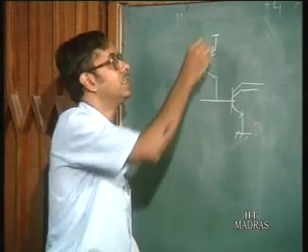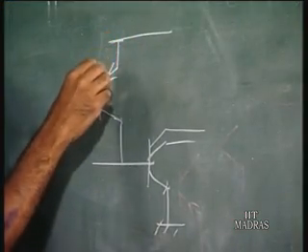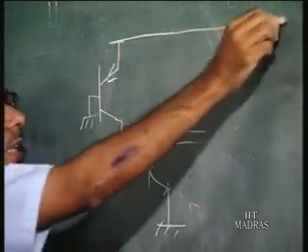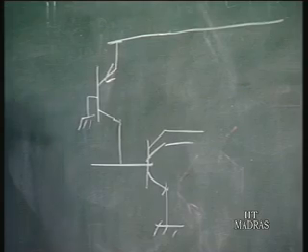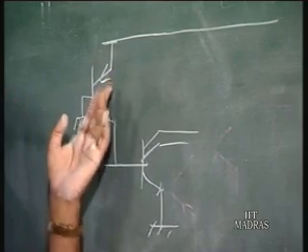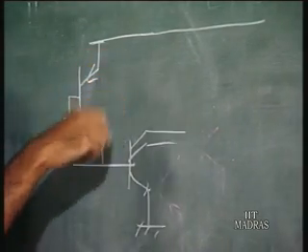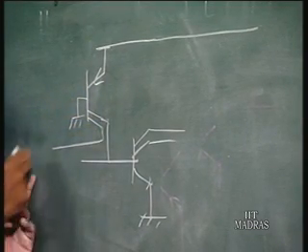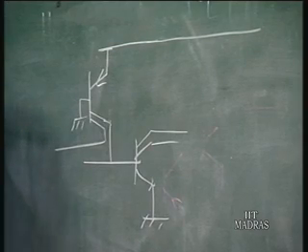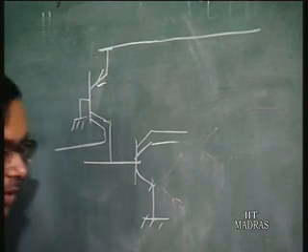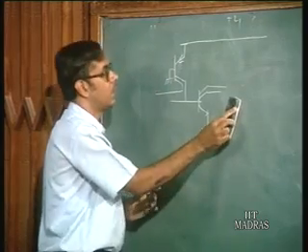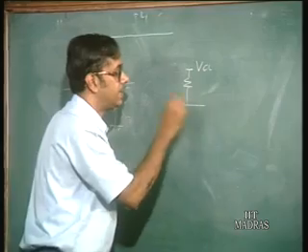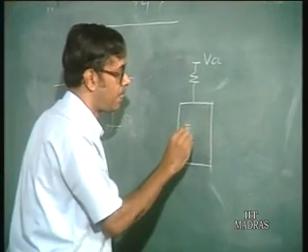So this is the emitter of the PNP, and if you have other circuits, all the emitters of the PNPs are common, and from there you can even consider this as a multi collector transistor, and this goes as current source to different nodes. Now, basically you can consider the I squared L as, this is a power supply, you have a resistance, and this is the I squared L block.